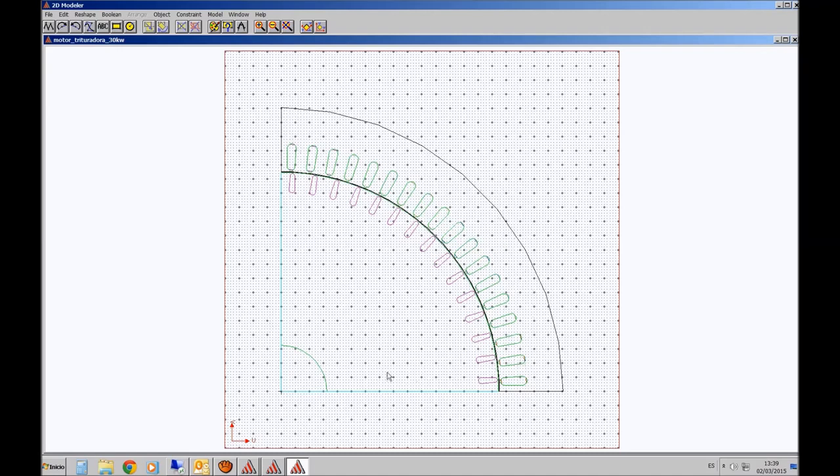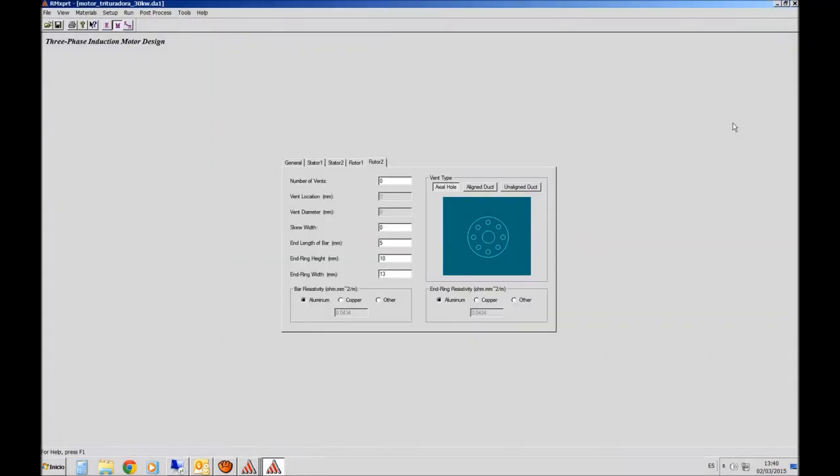So if you want to play with finite elements, it is much better to play with the complete model I will give you. But well, you've got a tool, and you can work with this. It's an approximate section that you then define materials for and can analyze by means of finite elements. You create a MAXWELL 2D project, and you can also use another tool called Simplorer, but it is not installed in this version. So let's go now to performance curves.